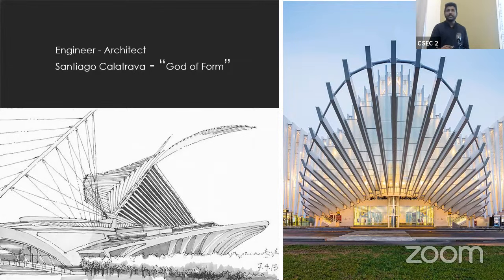So, okay, let's think we design something, a small house. You get the architectural drawing to locate the structural columns. You simply have, okay, what's the first step? You put the structural grid. As I know, correct me if I'm wrong. And you locate the columns as per the span, and you design the beam as per the span and the space between the columns, and the slabs as per the area.